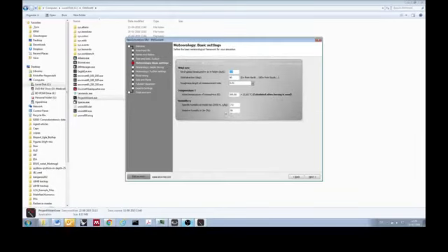In this section, we will define our wind direction and our wind speed. Wind speed at 3 meters per second is a low wind breeze, and 12 meters per second or above is considered harsh or stormy wind conditions. The direction is set to 90. This means that in our model, up is 0, and clockwise, 90 is from the right, and 180 is from the bottom, and so on.